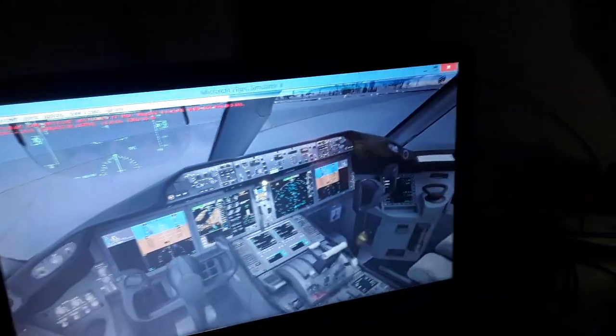So we're going to create a flight plan using the flight management computer. Later I will input all the data of the aircraft for this flight. It will show us a purple onward line we need to follow in flight, either manually or automatically using the autopilot flight director system panel.